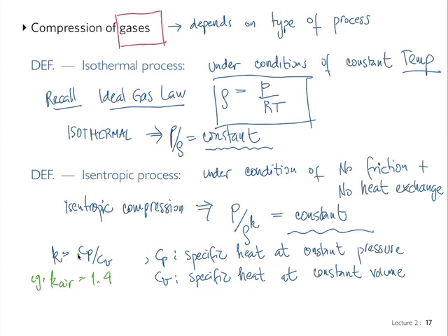And what did we say last class? What was another tip that we had for doing better on exams? That had to do with the ideal gas law. Very good. Always use absolute temperature and absolute pressure in your thermodynamic equations, in general.